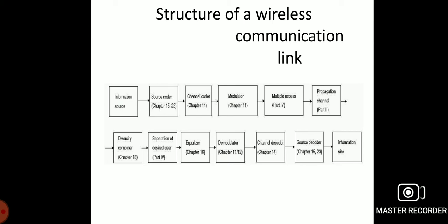The soft estimations are obtained by the decoder unit from the demodulator to find the original digitalized data. In conventional cases, the decoder is simply a hard decision device. For example, the Viterbi decoder is one example.